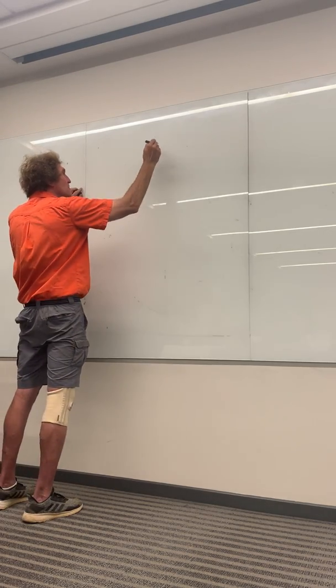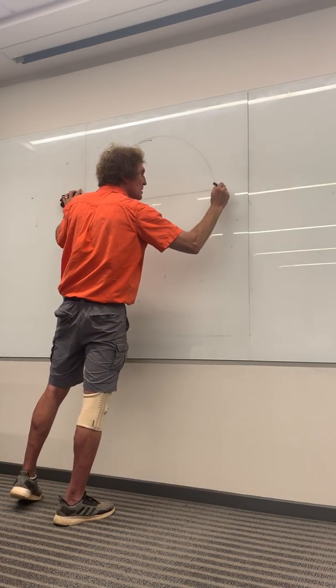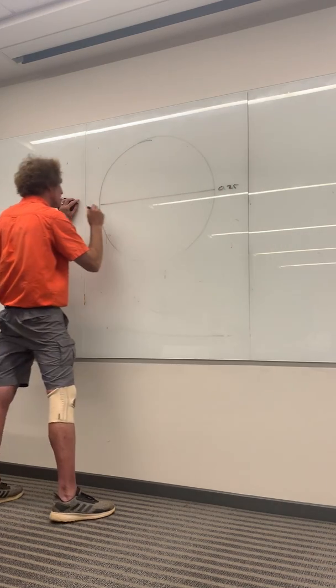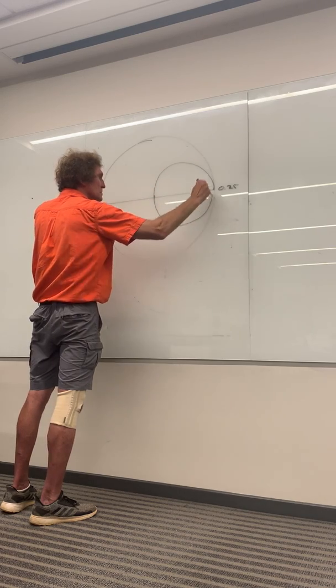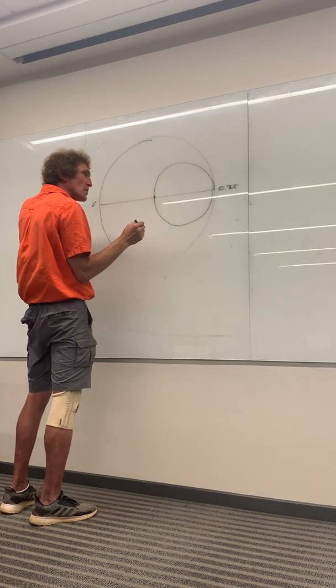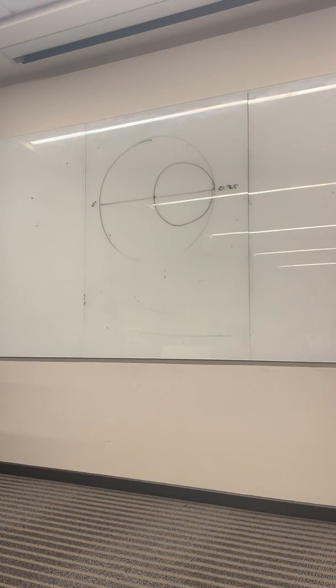All right, for this problem, get a Smith chart. And first, I need to normalize the load. So if I have ZL over Z naught, what do I get? That would be small zL. Can you tell me? 0.35 minus j0.5. So now I have to locate that.